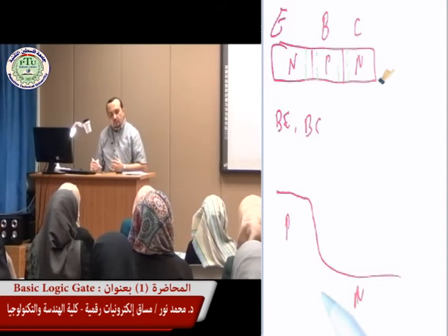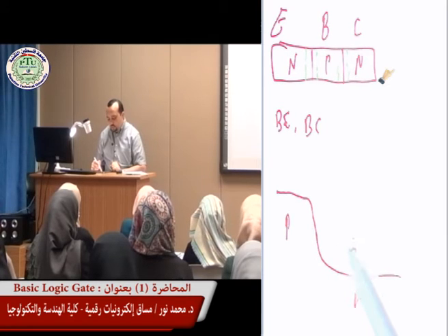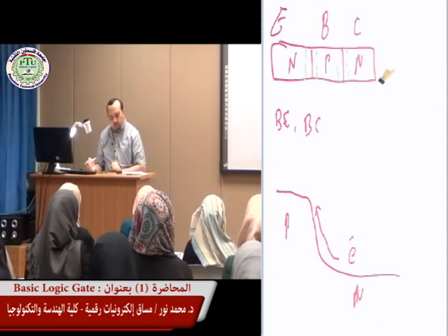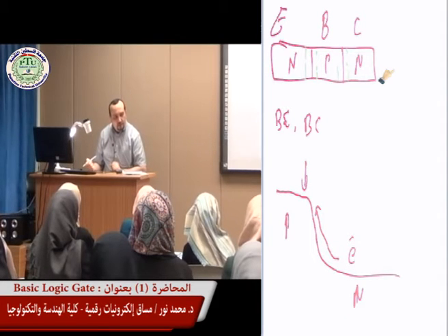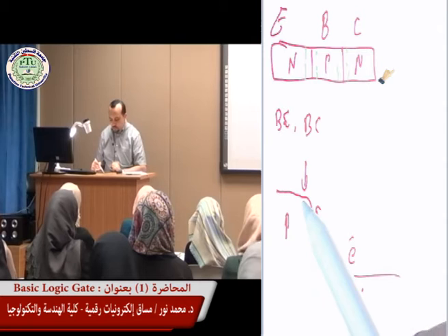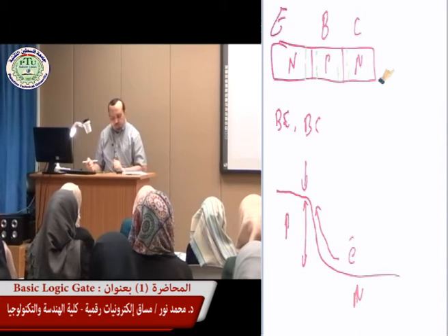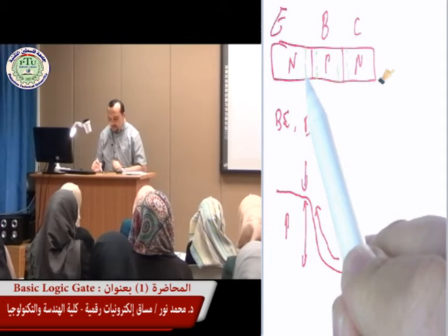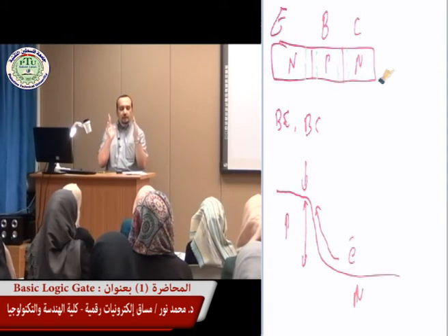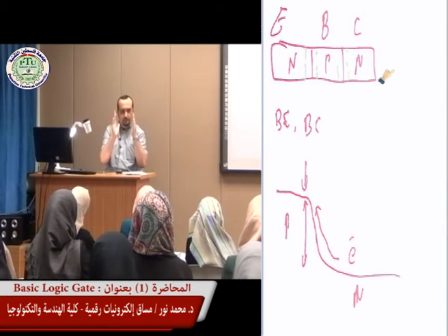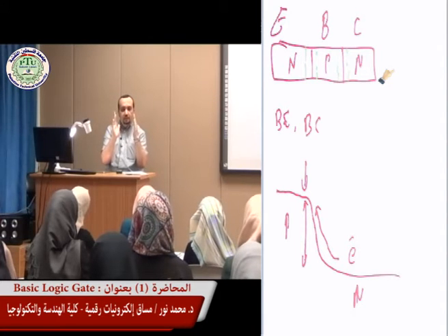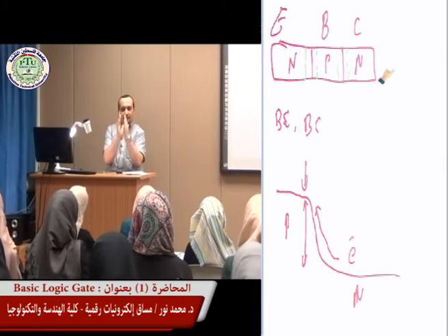Now, for the electron to start to move from this side up, we basically have to reduce this barrier, right? How do we reduce this barrier, which is this height? Let's say by applying positive voltage. So if we go back to the junction, let's imagine the depletion region like this: once you apply positive voltage, its width starts to shrink.